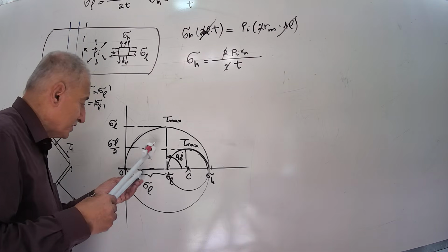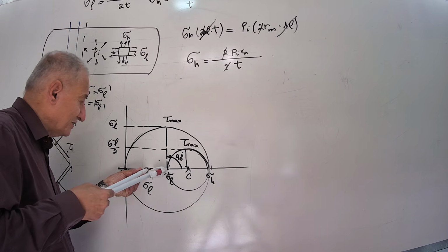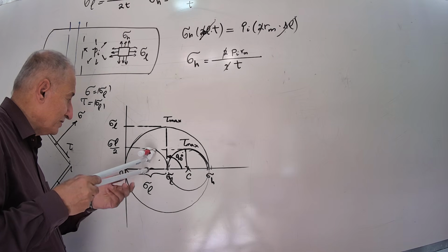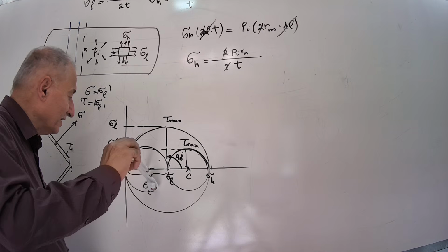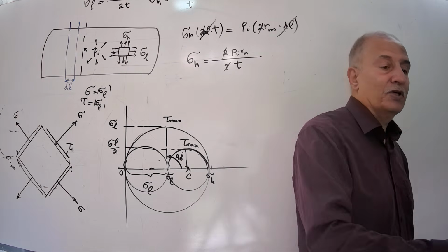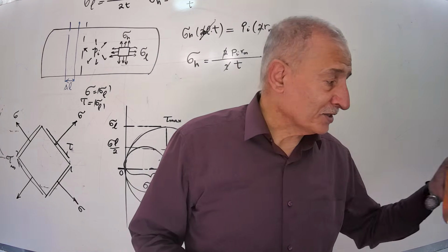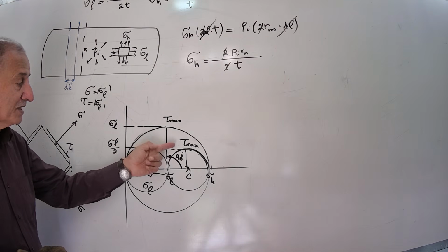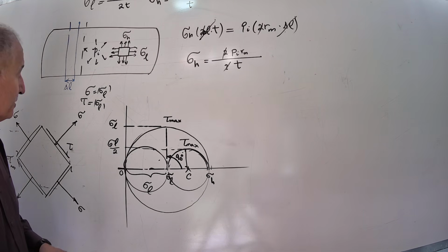We have another Mohr circle also here between the minimum principal stress and 0. 0 also is actually the minimum principal stress, not sigma m. If you draw a circle here, this is the complete Mohr circle for this case, which we call the three-dimensional Mohr circle. Then the designer must consider tau max here, and be aware of this value of tau max that is double the tau max that they expect.